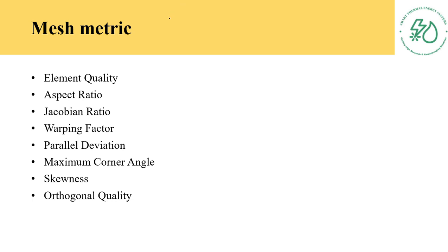After you mesh your geometry, you should check the quality of your mesh. There are some important parameters that you should check for your geometry: element quality, aspect ratio, Jacobian ratio, warping factor, parallel deviation, maximum corner angle, skewness, and orthogonal quality.